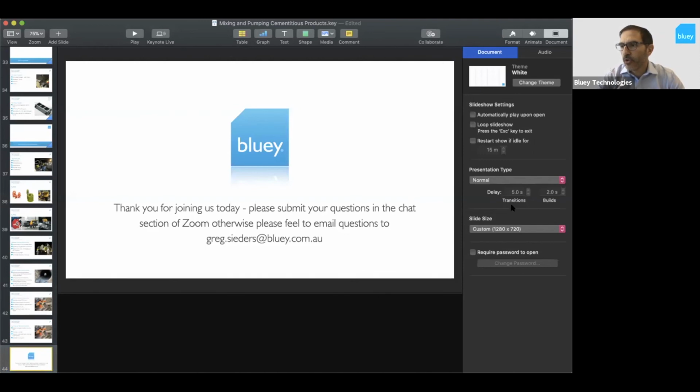We've got a question here from Ryan Young to you, Greg. Is there a stipulated size of grout cubes for compressive strength testing? It depends on the grout you're using. If you have a grout that has no aggregate in it, the standards call for 50 mil as the most common, 50 to 70 mil, and then there's 75s. If you've got aggregate in your grout, depending on the size of the aggregate, if it's less than 5 mil, you can still do 75 mil cubes, but any larger, then you go to 100 mil cubes.